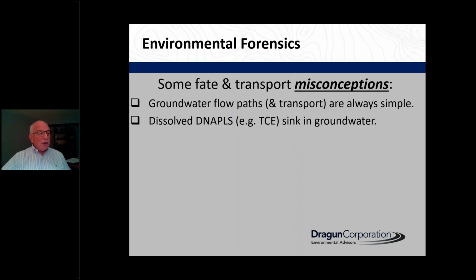Dissolved DNAPLs, dense non-aqueous phase liquids, like TCE, sink in groundwater. DNAPLs can sink in groundwater, but dissolved DNAPLs, dissolved like TCE, will not sink in groundwater. It will flow with the groundwater.